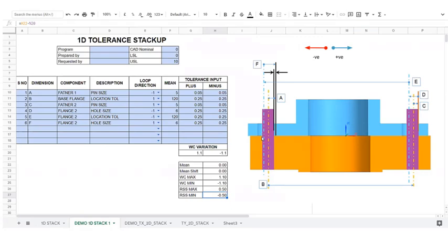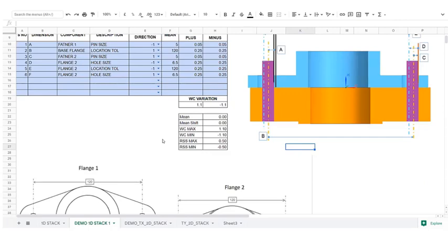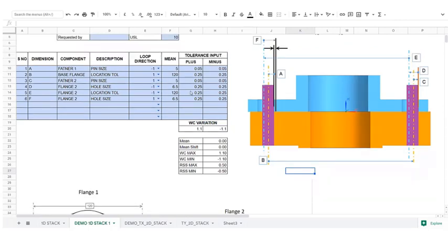The next solution is if it is a robotic assembly and there is no point of adjusting the part, then we need to give a different solution. Either we can increase the hole size or we can reduce the tolerance of it. So let's say instead of 12, our hole size is around 13. So we get a clearance of around 2 millimeters. I'm sorry, 1.5 I think. So that will be one way to solve the problem. And next, we can reduce the overall tolerance over here.